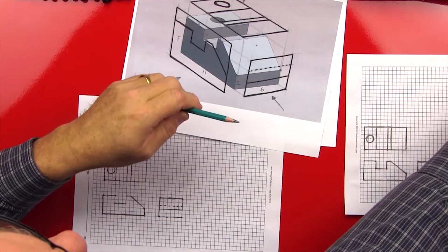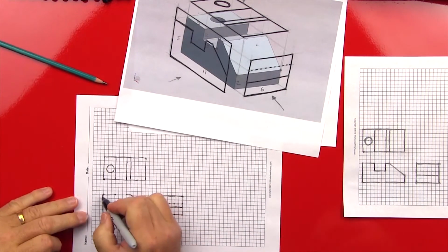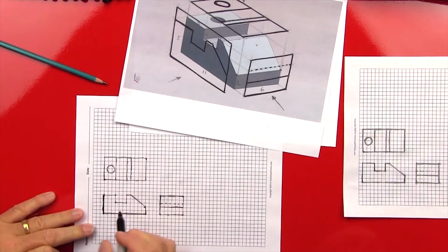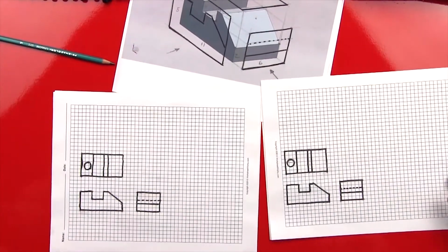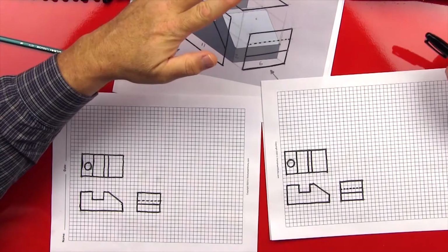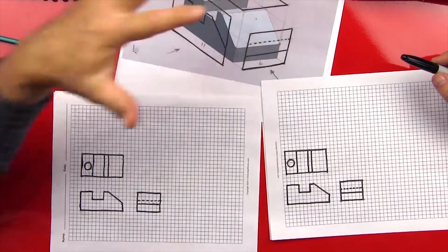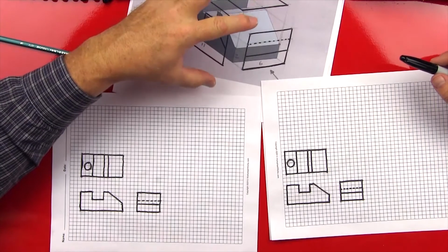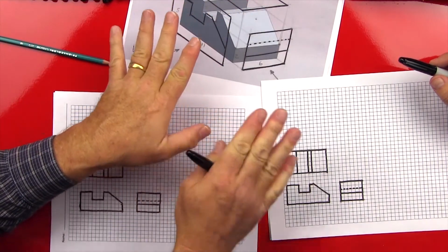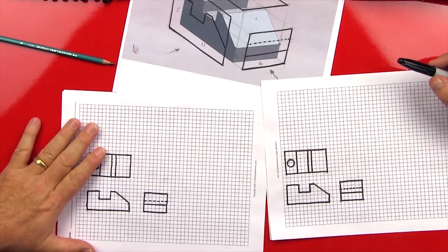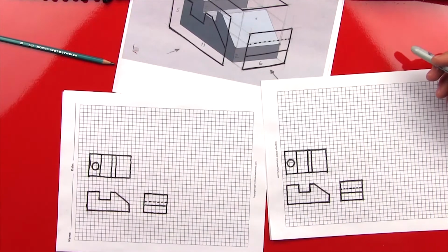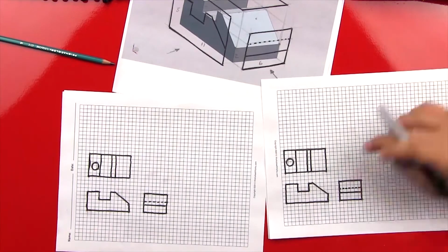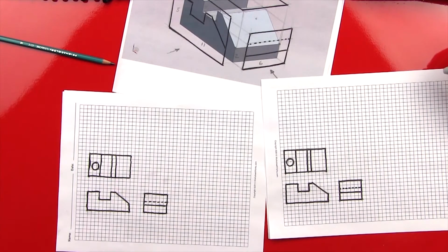Now, if we wanted to, we could take our Sharpie to darken these in because there are so many lines on the paper. It's pretty easy if you can visualize the planes that you project to off of this 3D image, and you're able to mentally unfold them, you can very easily lay them out very quickly on graph paper. That was a front, right, and top orthographic view. That was a lot of fun, and it was pretty easy, especially when you have the graph paper. You can easily measure things out. Great.